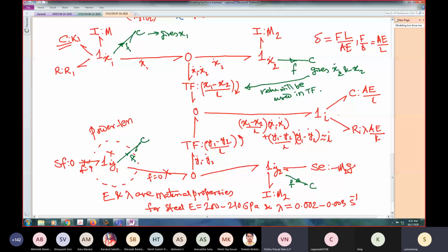Students: Yes, sir, the modeling is clear. Okay. So the zero junction takes the relative velocity, then multiplies with whatever factors and produces L dot. If it is 3 dimensional, you will take x1 minus x2 dot into this transformer, y1 minus y2. Similarly, another 2 pairs will appear, z1 minus z2. All of them have to be added at the zero junction.